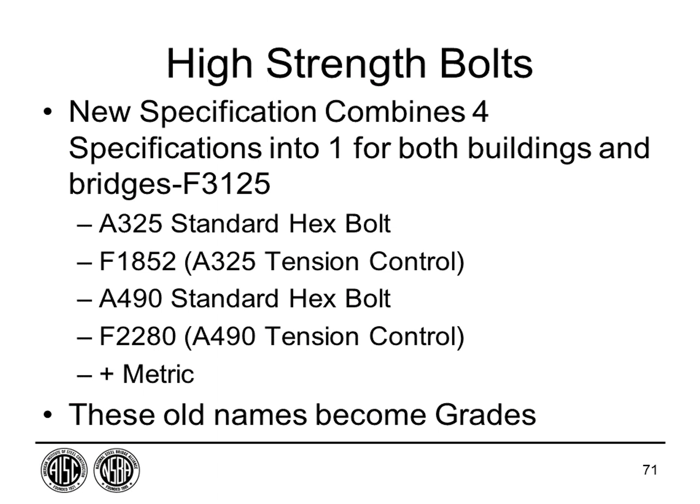Okay, great. The next question: for weathering steel connections, moisture between bolted connections has been a problem with bolts popping. Do you know if a solution has been found to prevent this type of failure? That's interesting. We actually did tests on weathering steel connections and never found that to be a problem if you properly tightened them. There's two things that have been found with weathering steel.